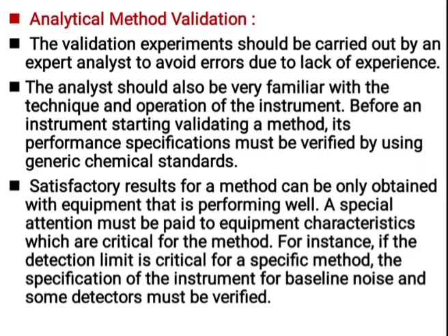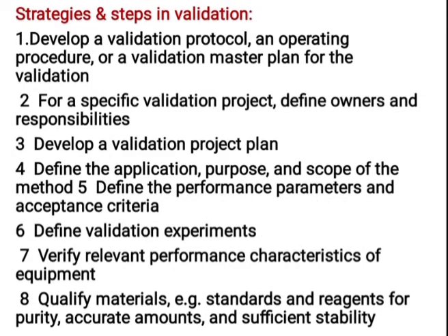Means obviously we have to check whether your machine is working well or not, and you have to pay special attention towards this. For instance, if the detection limit is critical for a specific method, the specification of the instrument for baseline noise and some detectors must be verified. Then see the strategies and steps which are involved in the validation procedure.